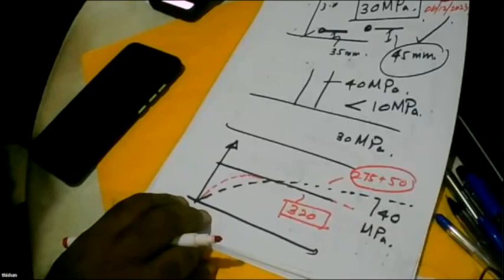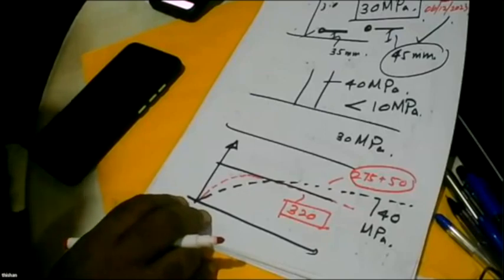You are creating a cover zone which is very dense, and when the cover zone is very dense, the pores are not connected, so the ingress of carbon dioxide into the concrete, with the reaction that we call carbonation, is very slow. Even after 100 years, you might still find the concrete is super strong and not affected at all, because the carbonation depths are very small. So that's why the curing of concrete is extremely important.